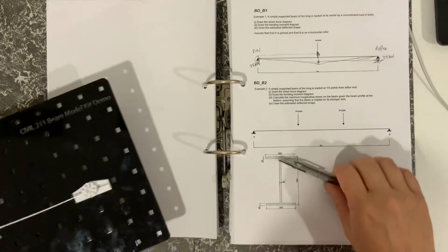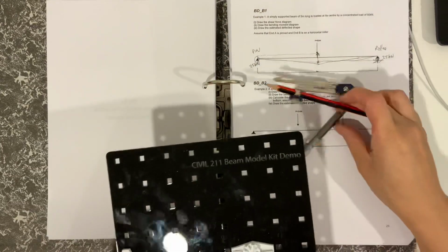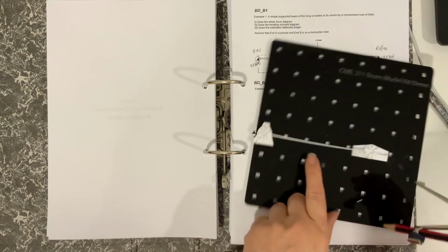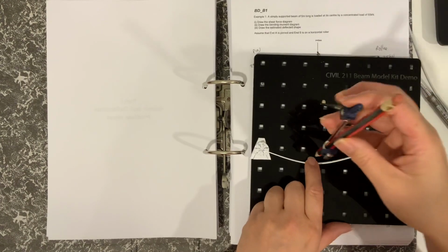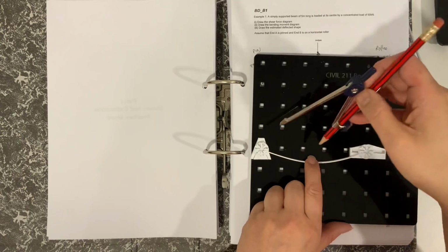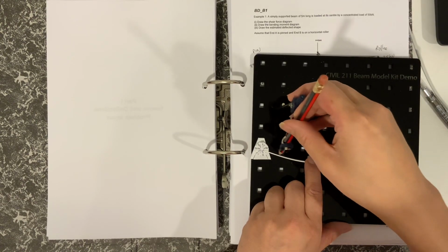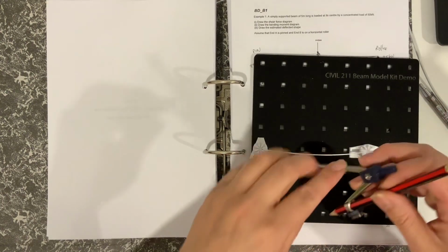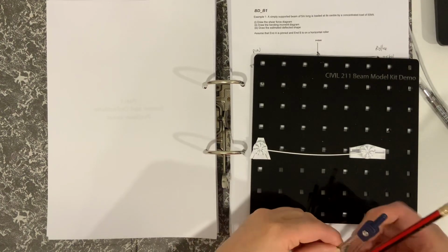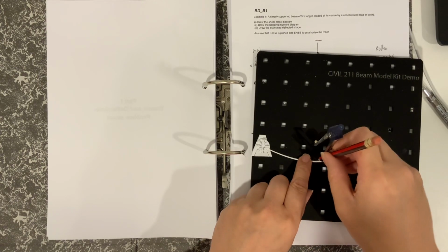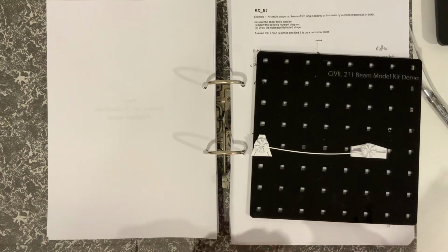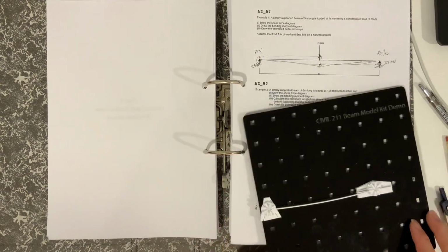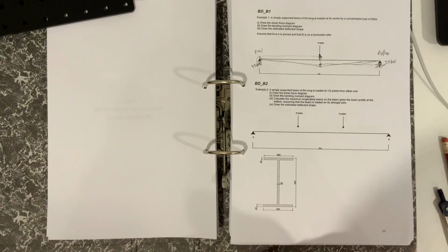If we took out the compass, as I showed earlier, you would expect the radius of curvature to be pretty large. Well, it would be infinity there, but you would expect it to be pretty large around here. So at these ends the radius of curvature is large, which means the curvature is quite small. Down here, you would expect the radius of curvature to be much smaller, because there would be more curvature at the center of the beam, hence the shape of the bending moment diagram.